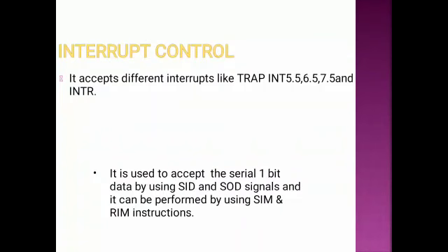Interrupt controller accepts different interrupts like TRAP, INTR, 5.5, 6.5, 7.5. Another is the serial input output controller. It is used to accept serial 1-bit data by using SID and SOD signals. It can be performed by using SIM and RIM instructions.